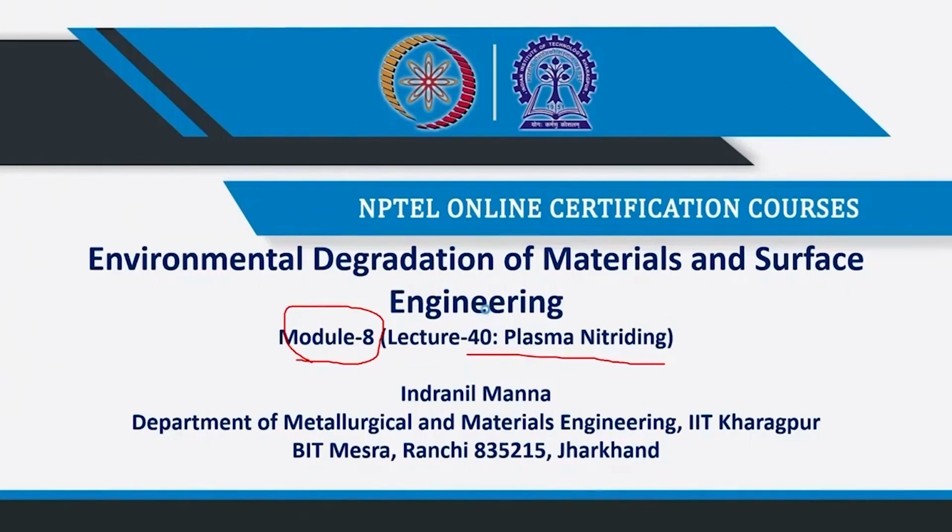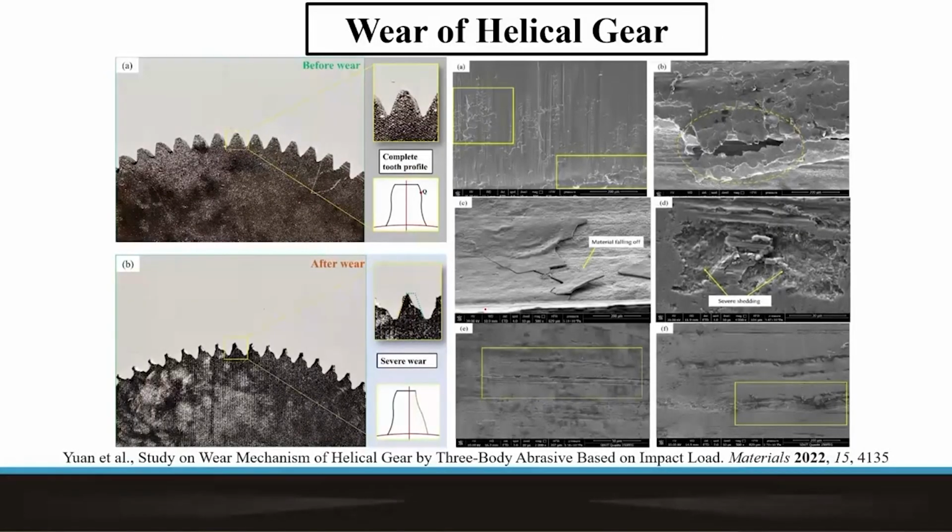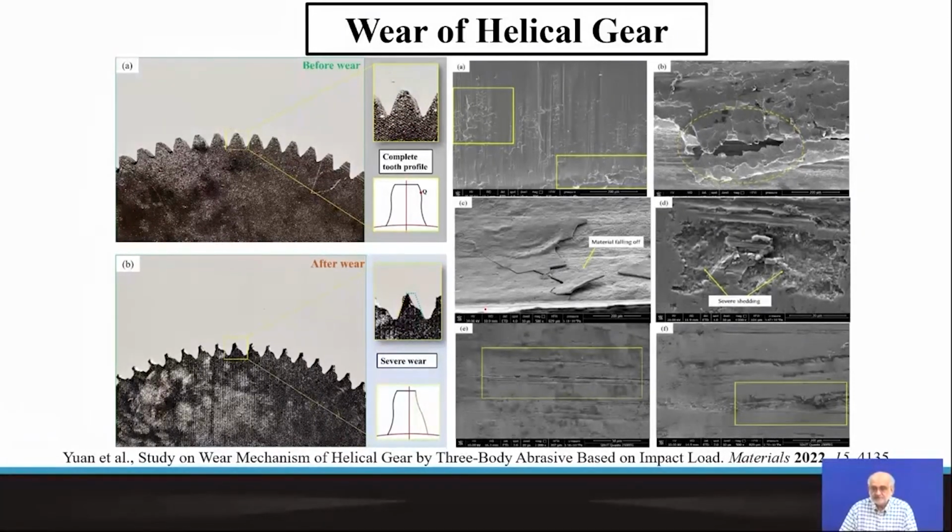So we have already discussed last time that when we introduce nitrogen to the surfaces of not only steel but any other element which has an affinity for nitrogen, be it iron or titanium or chromium or aluminium or molybdenum, any element which has nitride forming ability, and is exposed to high temperature containing nascent or atomic nitrogen, is likely to form initially a solid solution.